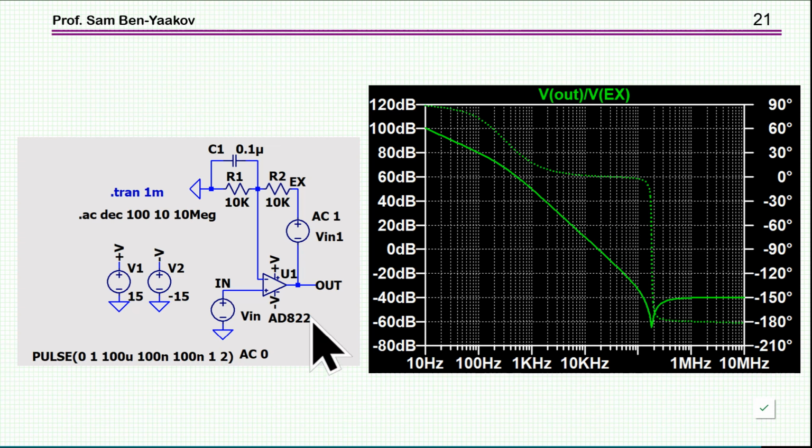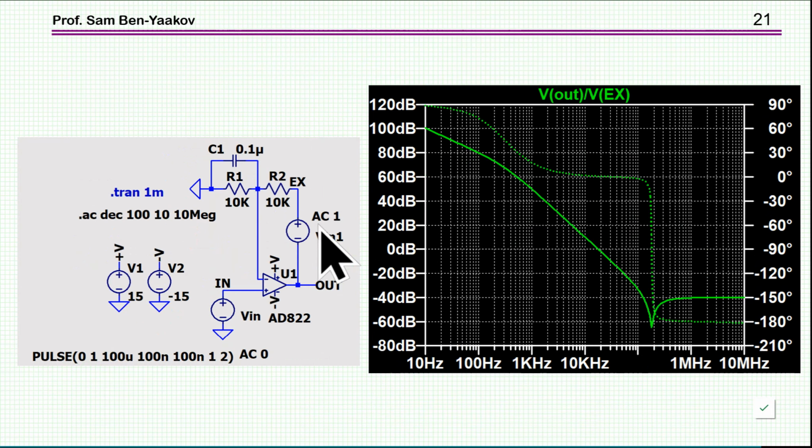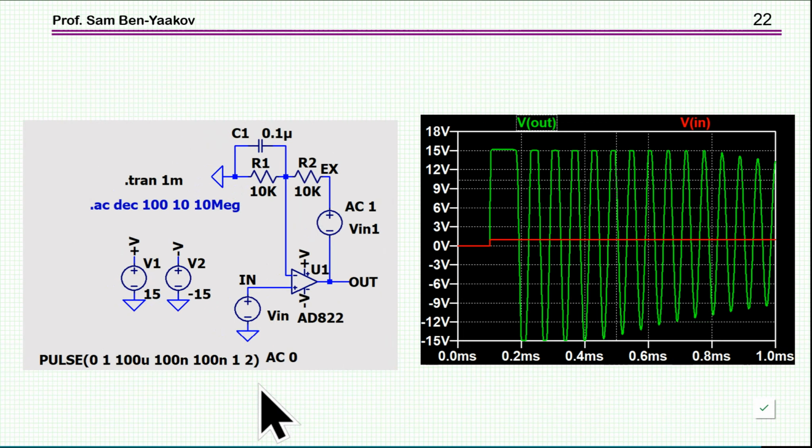And the reason, as I have said, there is a phase lag here of about 90 degrees at high frequency. There is a phase lag here, and the amplifier itself, let's have a look at the amplifier. Here's the amplifier. This is the phase of the amplifier, 90 degrees. And therefore, it has a phase margin of 0. And to test this, what I did here, now I've converted this source to be a step. It's a pulse of 1 volt. Here it is. And you see, I'll give it here a step, it starts to oscillate, okay?